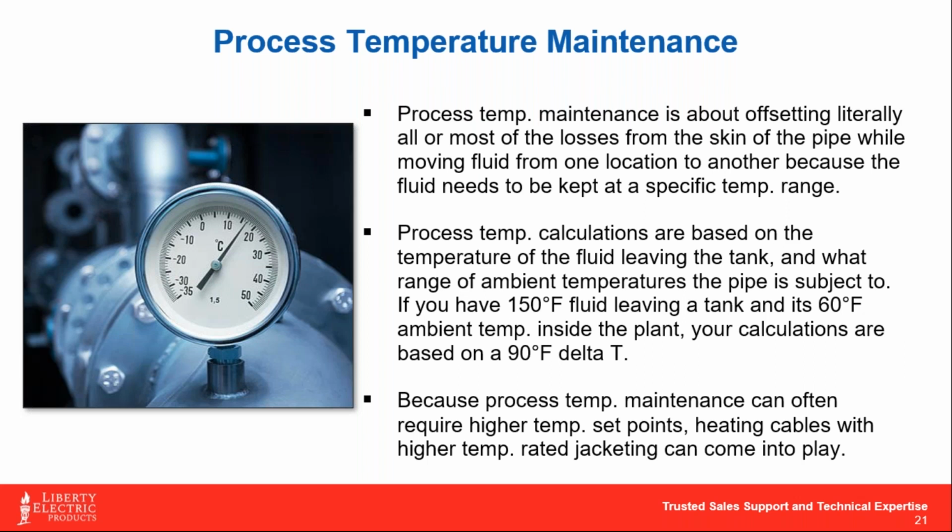But I can't say that, if that was sitting stagnant in the pipe for an hour and your heat trace cable was running for that hour, that you wouldn't add heat to it. But basically what we're doing with this particular application, when you think about it in terms of design, is: what's the fluid leaving the tank at? What do we need to maintain before it gets to the nozzle of the sprayer it's going to, or the filling machine, or whatever it is that you're processing in that plant? It's what's the temperature it needs to be at by the time it hits point B.